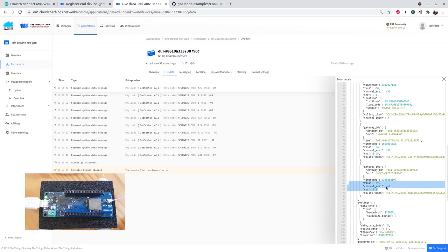This specific gateway is actually on my roof, so we've got metal roof tiles between the device and the gateway. Without an antenna, the signal doesn't want to travel through those metal roof tiles. But with the antenna plugged in, we actually get the signal through, and it's going through quite well.